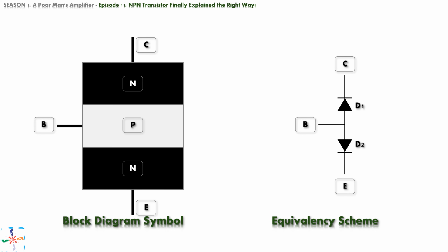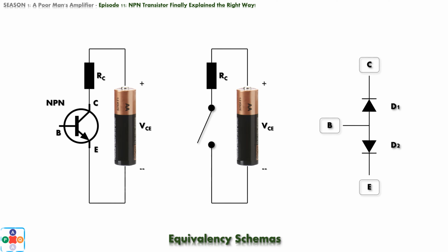two diodes are placed in series. Please beware that in real life, if you place two diodes like this in your circuit, you will not get a NPN transistor. This model of transistor, with two diodes, is just for explanation of base cutoff current purposes only. By definition, the base cutoff current is the current flowing from emitter to collector terminal, when voltage is applied across collector and emitter, but there is no voltage at the base terminal.